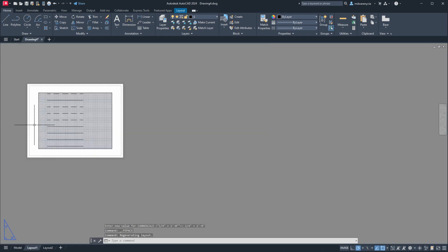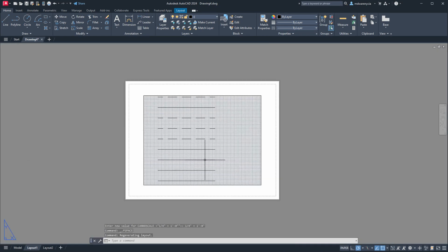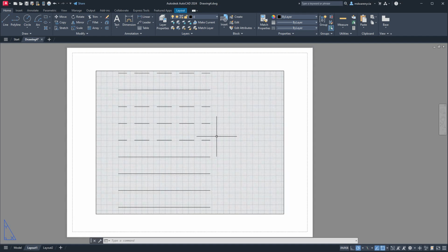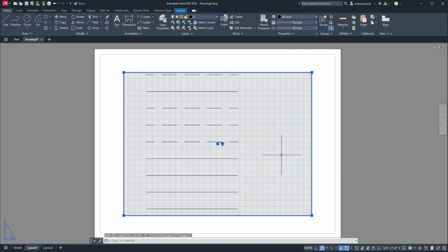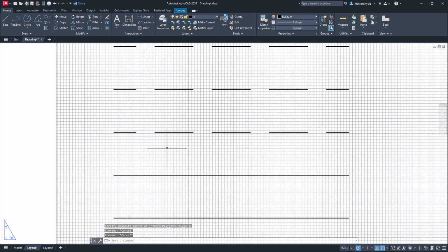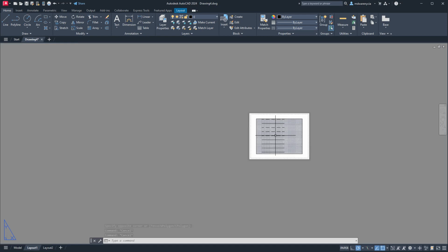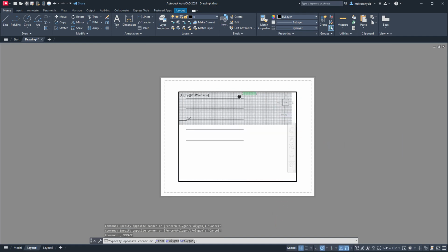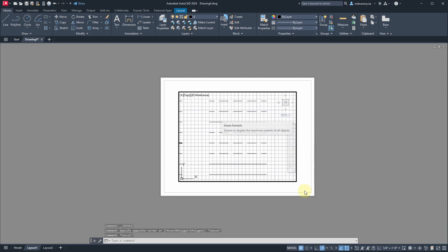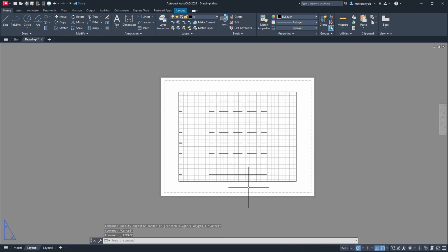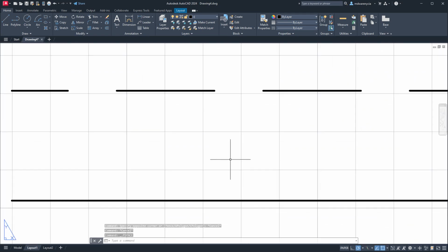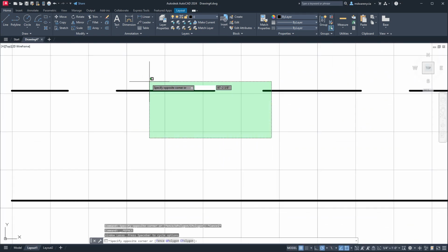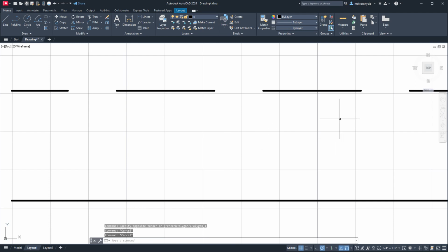That just reminded me of something I want to point out. I guarantee every semester I get this problem, and that is that someone zoomed in on a viewport, which is what this is right here. We'll talk about viewports in a second. They zoom in too far, and typically when you're working with them, you want to be able to see the outside of them, which is this border right here. You would double click inside of them, and now I can move around inside of there and manipulate things, and then double click to get outside. What happens is someone will zoom in too far, double click, do whatever they need to do inside of here, and then now they can't get out.